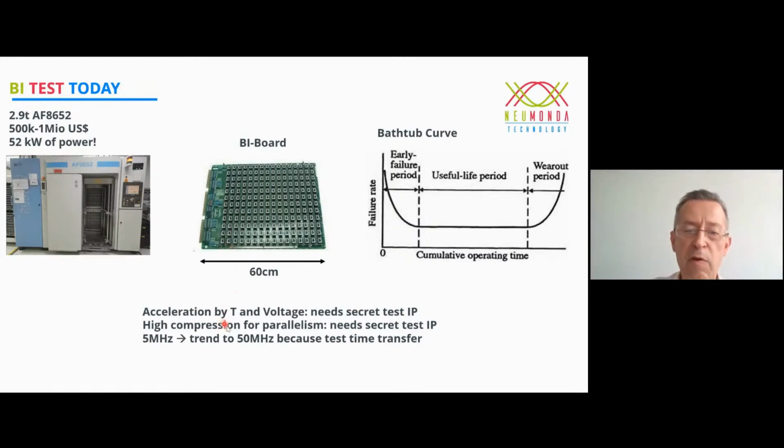So in burn-in testing, we raise the temperature to very high values. That gives you an acceleration factor of 10, 15, and we increase voltage. If the external supply voltage is 1.5 volt, maybe you go to 2.5 volts to stress your semiconductor, the silicon, any weaknesses. That gives you another voltage acceleration, depending on your semiconductor properties, 10 to 20. So those two factors combined give you a very strong acceleration factor. And then in a 10-hour test, you try to simulate 3 months of lifetime.